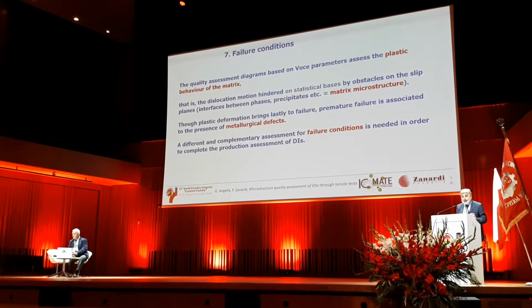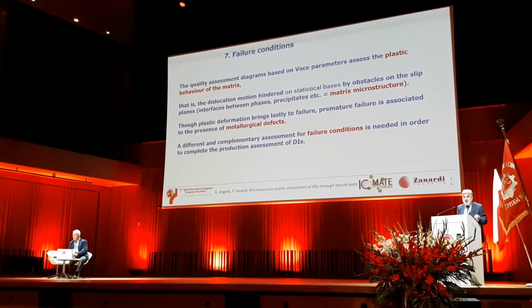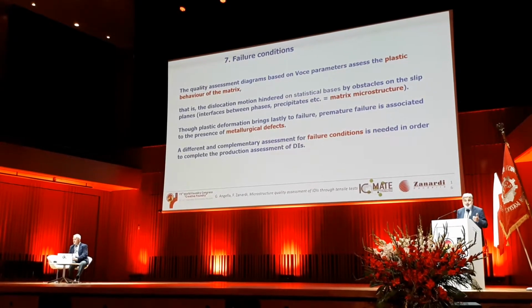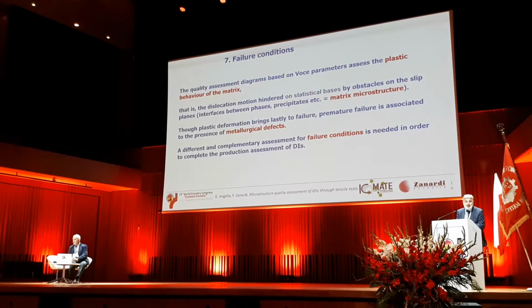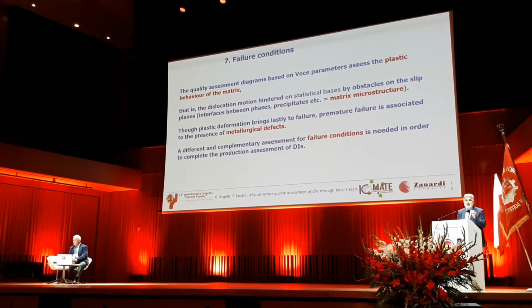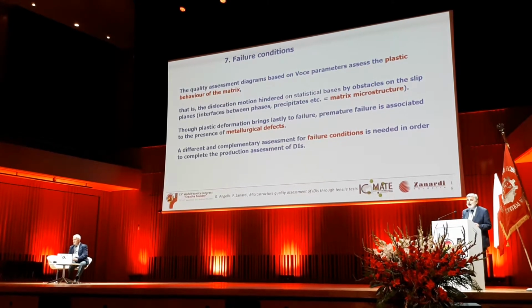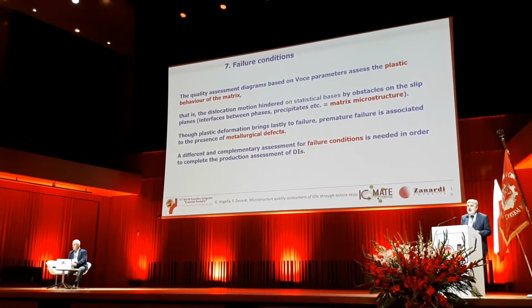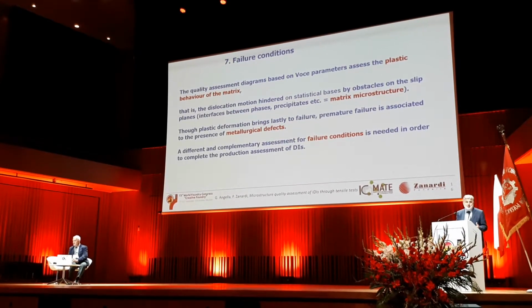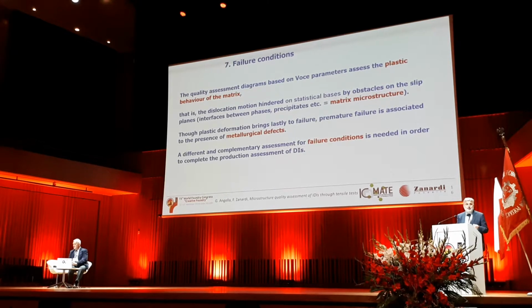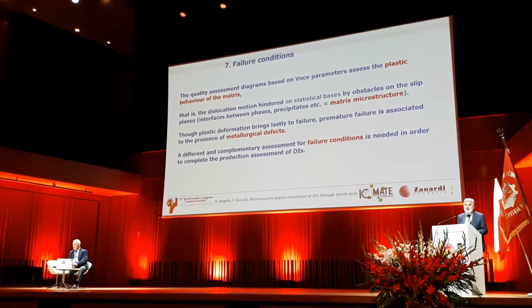Okay, and with this VOS approach, with this matrix assessment, we are able to assess the matrix independently of the presence of small defects. You know that one of the main concerns we have in our normal day life is that elongation at fracture is very dependent on the presence of very small defects.